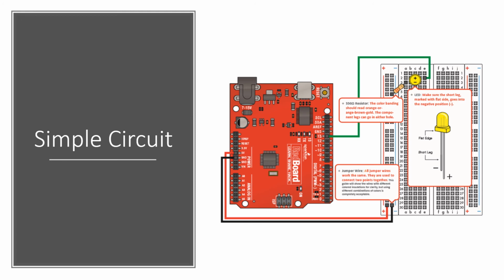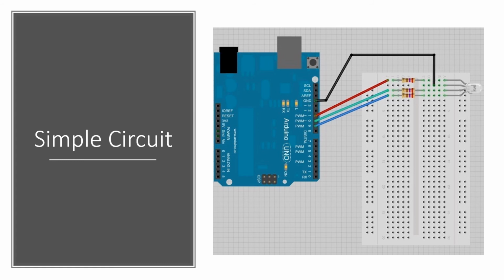Here's another case, an RGB LED. In this case, the power is coming from pins 9, 10, and 11, coming across through our breadboard, being fed through the resistor over the gap to this row, into this LED lead, into the LED, and out through the common cathode to the black wire that returns to the ground.